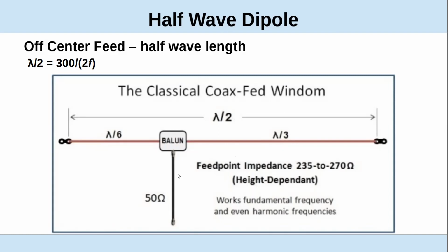If it's 20%, they'll give you a 5-to-1 balun. And I think the only one who's really doing the 5-to-1 balun a lot is Chameleon. But the benefit isn't directional, it's still omni. Well, it's the same sort of pattern. Yeah, the pattern then is broadside to the antenna.